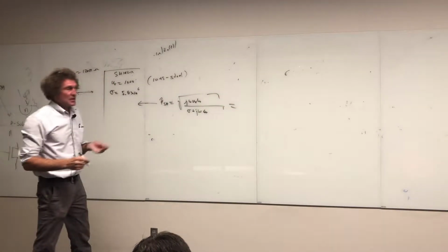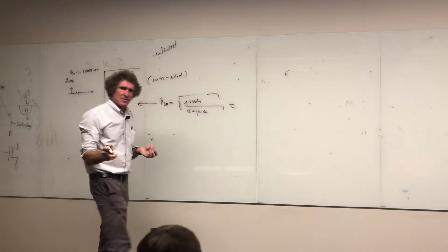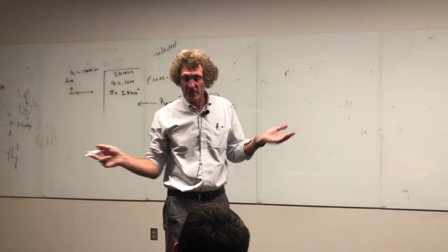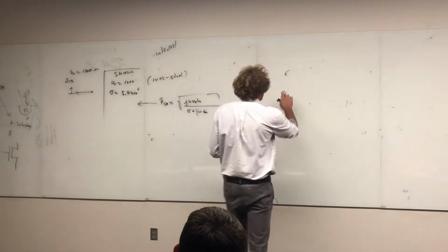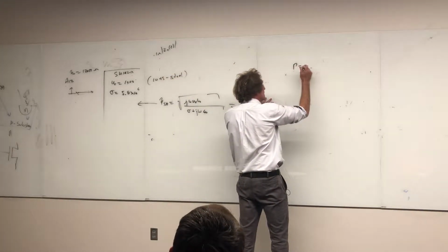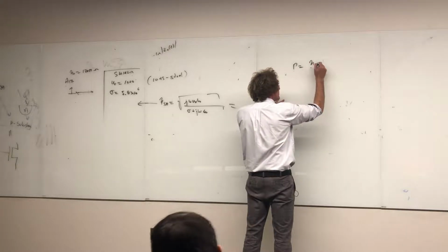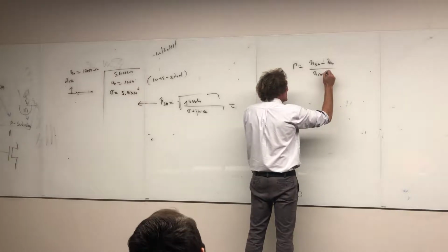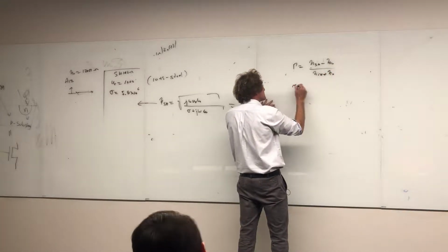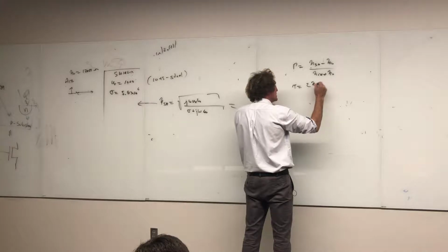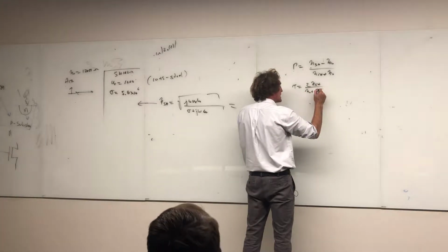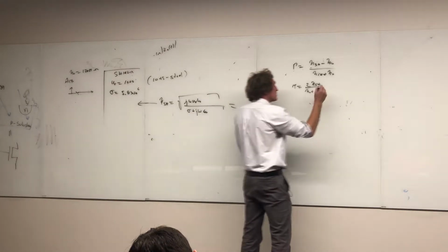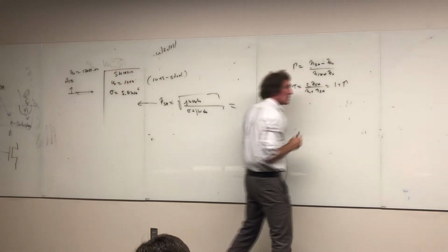And what he does is he said he wants the reflection coefficient, is that right? Just tell me. Yes, he wants the reflection and then the transmission coefficients, all right? Well, these are pretty straightforward because reflection coefficient is equal to eta shield minus eta naught over eta shield plus eta naught. Technically, the transmission coefficient is 2 eta shield over eta naught plus eta shield, right? These are the formal ones, right? Or you could put it as just 1 plus reflection coefficient. Do y'all agree with that?